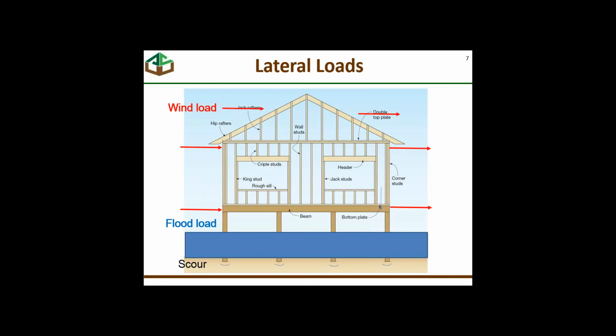So when we have a hurricane or a tropical cyclone system of some sort, and we have wind blowing at the same time we have flooding, we do have a wind-water interface, and typically there's very little overlap of that interface except what might occur where waves strike buildings, etc. So where we have wind loads and flood loads, those are going to occur sort of not independently, but they're going to occur on different parts of the building.